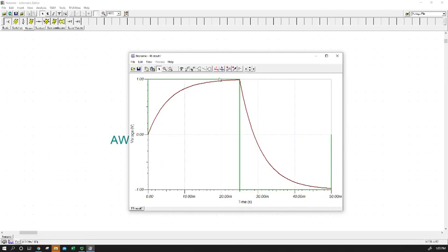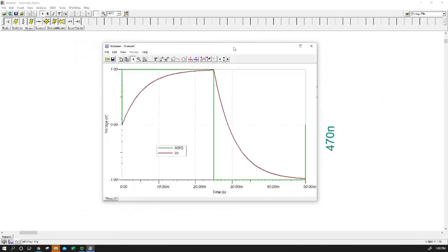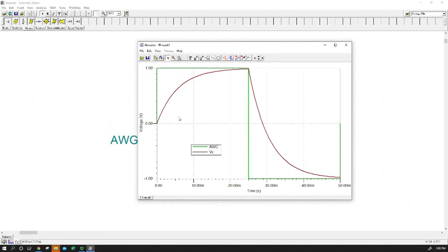So you can see in green we've got our excitation, so there's our square wave, and we can display a legend here. You can see that the burgundy or brown line is V sub C, which is our measured voltage over the capacitor. And so the waveform looks pretty much exactly what we would think it would. On our forward going waveform, the capacitor's charging, and so we have this negative exponential relationship with time. And then when we reverse the voltage, this is like the scenario that we calculated in our earlier video, where we change to a voltage source going in the same direction as the charged capacitor, and we let current flow in the other direction, and now we have basically the opposite direction attenuating signal, and then we eventually reach almost steady state here before we switch the waveform again.